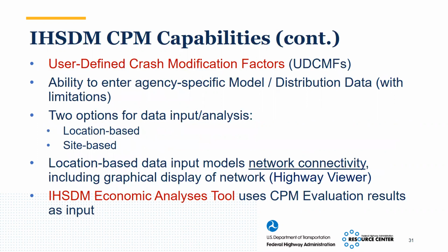User-defined crash modification factors. This is something that we'll talk about more in a minute, and then we'll show in terms of our demonstration. You'll see this come into play, but this gives the ability to go beyond what's in the HSM Part C methods by having users define these crash modification factors as needed. Also, the ability to enter agency-specific models or distribution data, and there are some limitations to that.